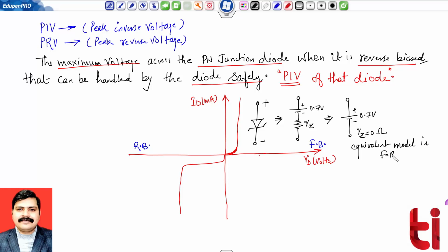Forward bias. Likewise, the structure in the reverse bias is now we are giving positive voltage to the cathode and negative voltage to the anode, and it will be represented by an open circuit. So you can check the functionality is same as we have seen in the ordinary PN junction diode. And I'm marking this reverse bias region up to this level only.